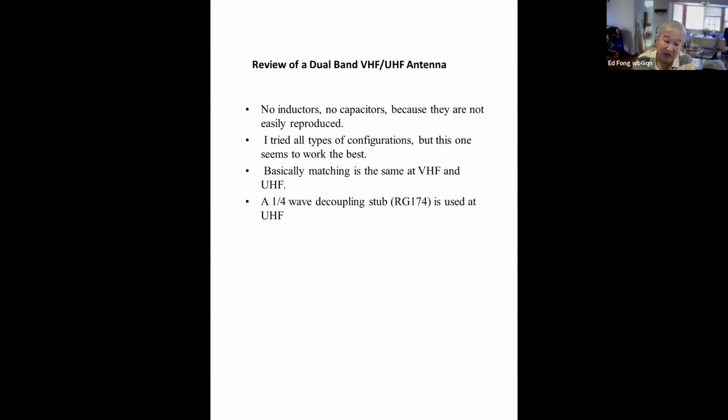But as you start raising the frequency, as you guys probably know, you'll start seeing series inductance, self-resonance, series resistance. By 500 megahertz, you can hardly see any of that 6 picofarad left. It's got too much series losses and resonances. So you cannot require that. That's out of the question for any antenna up in those regions. It's just not practical. You have to do it through transmission lines or some kind of T match, delta match, or something like that. So anyway, I tried a lot of configurations. I'll show you what we came up with.